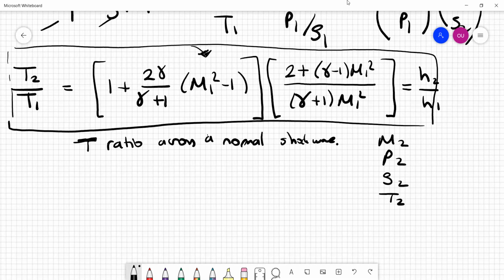And in order to make your lives even easier, or our lives as aerospace engineers even easier, the results of these relations are already calculated and tabulated at the end of books. For example, if you look at the end of your aerodynamics book, you will see tables listed under the name of normal shock wave relations, and for air, for example, given gamma, for different M1 inputs, it's already calculated in the table.